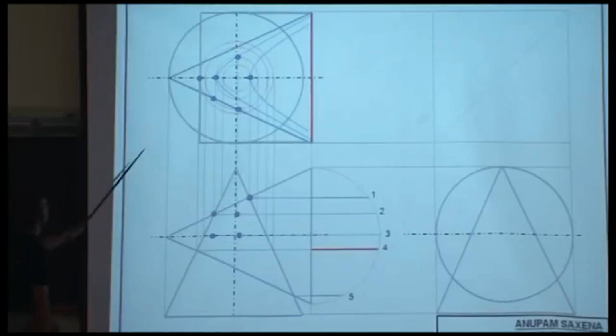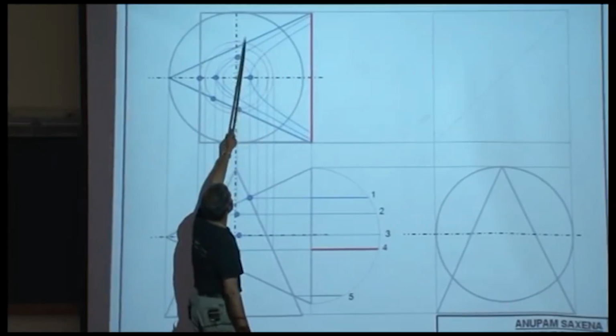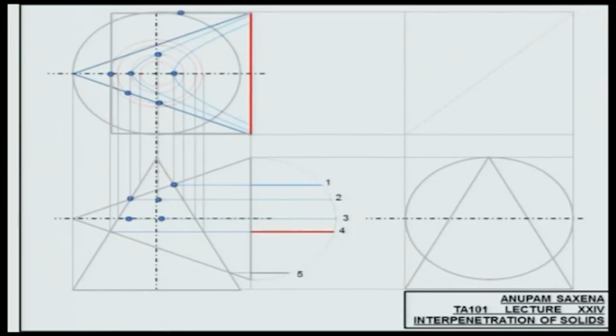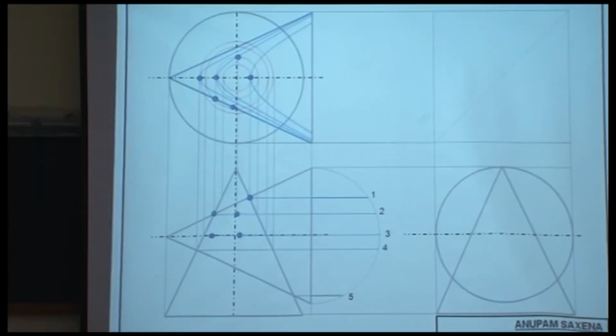Divide this edge into equal number of parts, that edge into equal number of parts. Start joining the lines, find the intersection points. You'll have 4 intersection points in all, or 4 points lying on a hyperbola in all. Draw that hyperbola, draw the mirror image of that, find the intersection between the corresponding circle and the hyperbola.